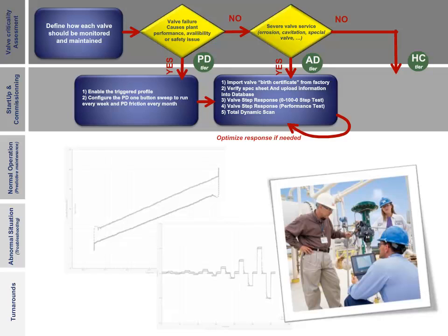1. Import valve birth certificate from factory. 2. Verify spec sheet and upload information into database. 3. Valve step response, full stroke. 4. Valve step response, performance test. 5. Total dynamic scan.